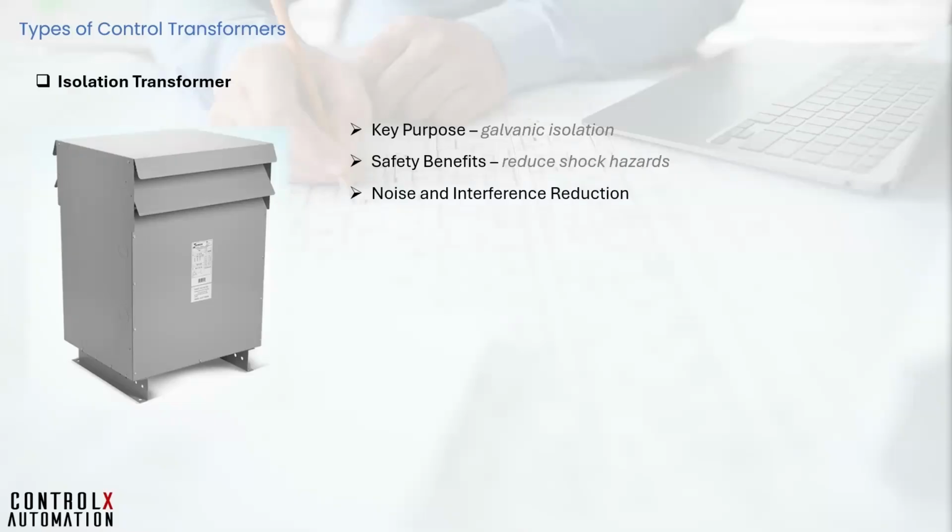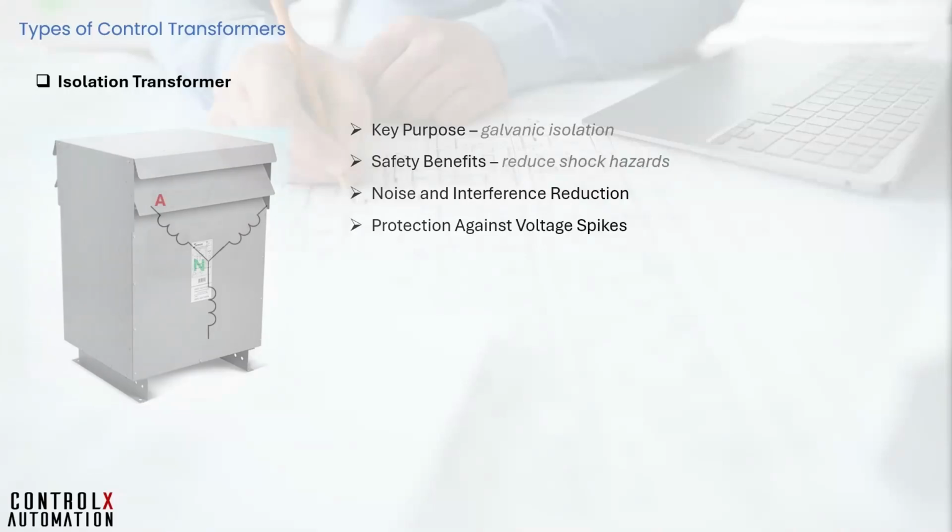Another important purpose is mitigating electrical noise and interference. Power lines often carry unwanted spikes, humps, and transients from other devices. The isolation transformers separate windings and magnetic coupling, block high-frequency noise and ground loop interference, providing a much cleaner and more stable power supply source for sensitive electronics like computers, medical devices, and lab instruments. Isolation transformers also reduce voltage spikes and transients caused by lightning, static electricity, or sudden load changes. The inductive properties of the transformer windings act like a filter which prevents rapid voltage changes from directly reaching the load, thereby protecting connected equipment from potential damage.